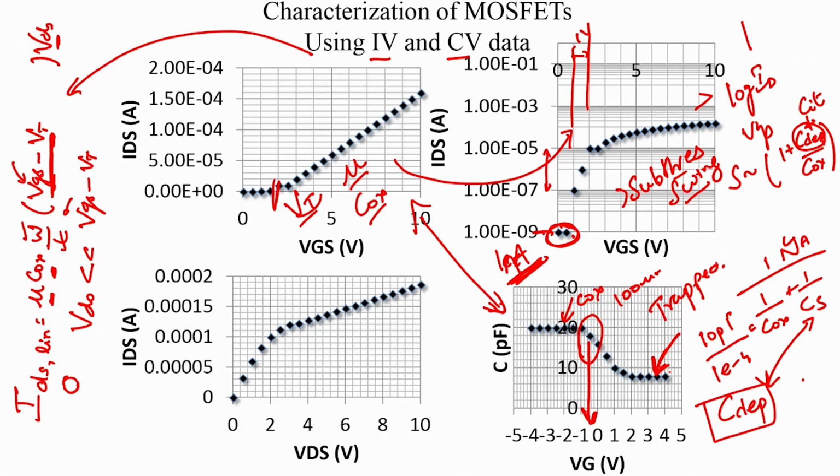So, now finally we will plot the output characteristics. Since we already know mu, Cox and Vt, we can cross check to see whether the output characteristics in linear mode match the use of these parameters, and you can iterate between all these plots in order to see whether we have the right parameter set. But in saturation mode we look for two other features.